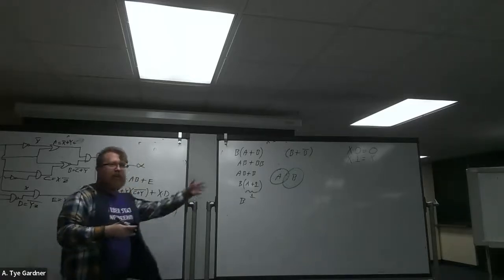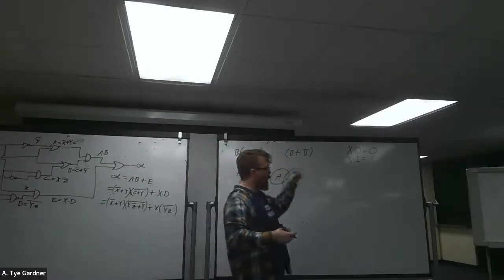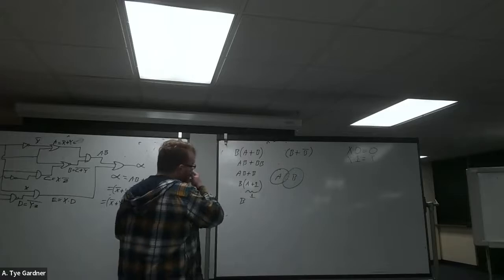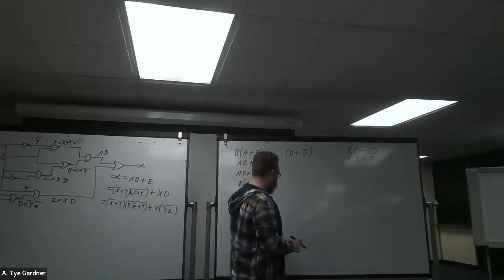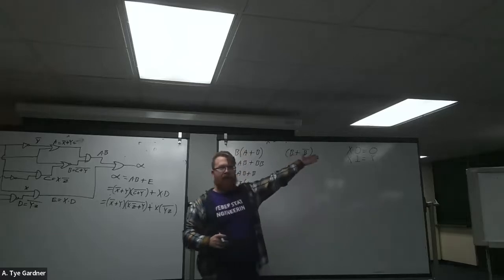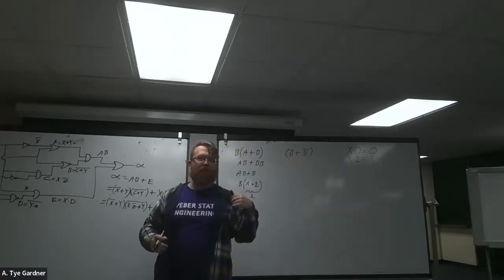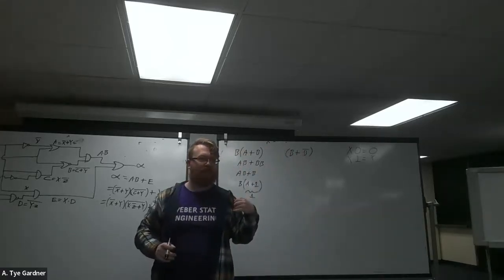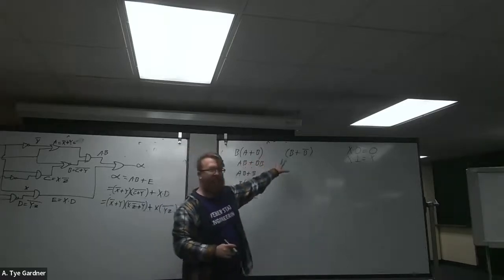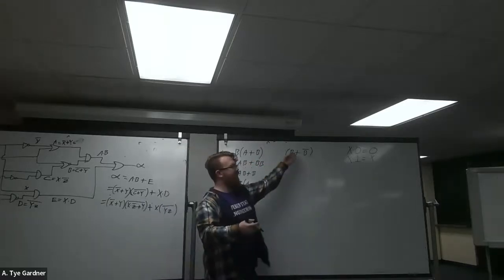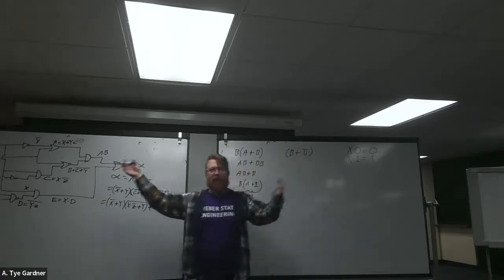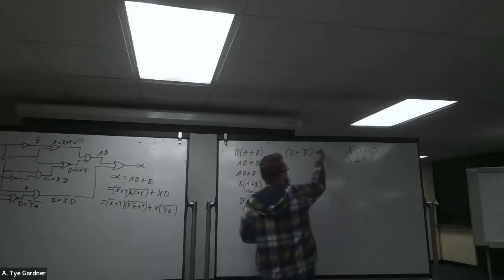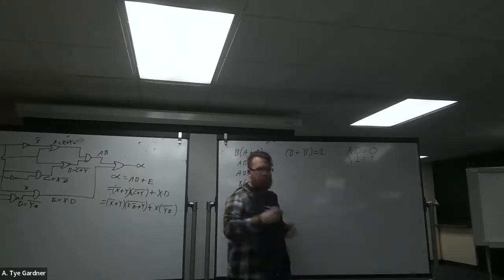This is where the Venn diagram can come in helpful sometimes if you need to think about these simplifications. Well, let's go to the next example that I was going to do because this one is kind of fun. B or not B. When is that going to be true? Always? Or is there also an A, are you implying? There's no A implied. Oh, anything, then just always. Always, right? Always. Because if B is 1, it's true. If B is 0, then not B is true. So I can't be false. So B or not B is 1.